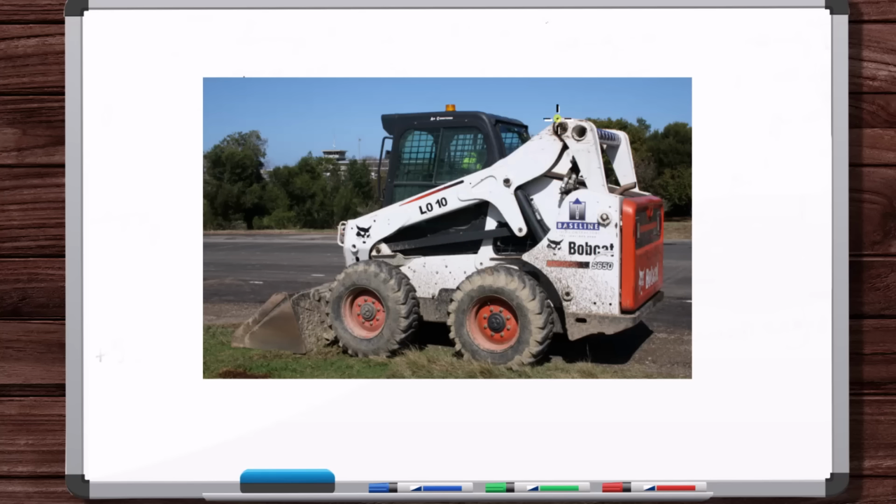When we bring this connection into empty space, it depends on the snapshot in time that we do this. So we could bring it into empty space right now where there's no load on the machine, the shovel is down. But more commonly, if you're designing this machine, you'll look at a standard operating scenario: a standard load in the bucket, raised to mid-height.